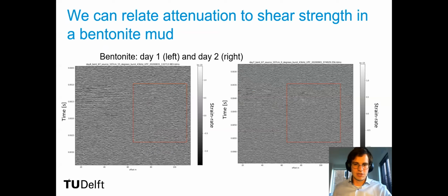we observed a wide variety of other phenomena, including these really wacky hyperbolae that are really hard to interpret. And the interpretation is that these are from a secondary source of scatter. But as you can see here, the degree of interference between the direct wave and the secondary source of scatter means that we really can't tell what's going on from this sort of visualization, that measuring the dispersion in this kind of configuration doesn't work well. And so we opt for a different form of visualization, which works very well.